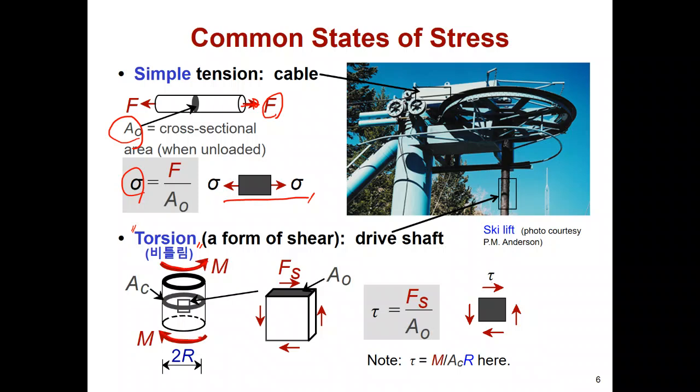So this is a moment-like behavior. At that time, this is some cross-section surface. When you check a unit solid volume element, this cross-section area will show this kind of shear movement, so this acts like shear forces, so that this solid metal can exist in the shear stress state. The shear stress can be defined by the shear forces divided by the cross-section area.